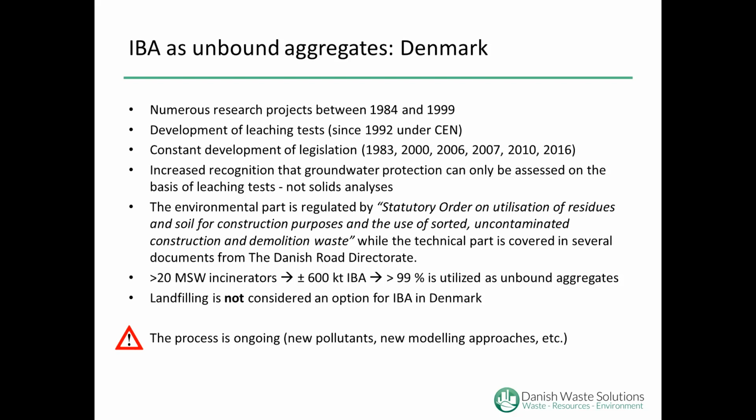Today, there is approximately 600,000 tons of bottom ash generated in Denmark from more than 20 incinerators. 99% or more of this mass is actually utilized as unbound aggregates. So landfilling is not considered an option for IBA in Denmark, and it has been done this way for years. And it's important to stress that this whole process is an ongoing process. If there are new pollutants, we should include them. If there are new modeling approaches, we should include them as well. So it's not a static process, it's always developing.